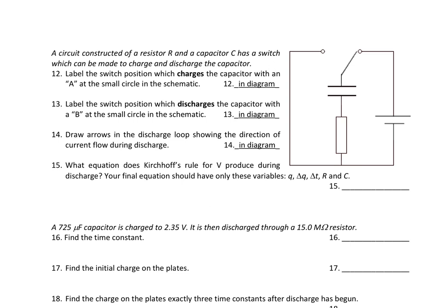So in the current position where the capacitor and the resistor are connected to the power supply, that's the charging condition. You said to label that with A, that connects it to the battery, and then if you wanted to discharge the capacitor, you disconnect the circuit from the battery, so then the capacitor is able to release its voltage, discharge, and that would be the B position.